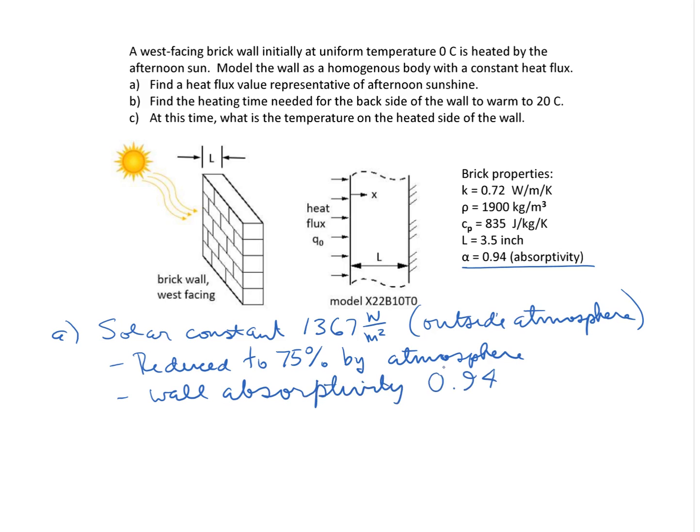And we've got some geometry here. If the sun were right overhead, that would be noon here. If the sun were down here, this would be 6 p.m. Let's say that the sun is somewhere in the afternoon, call that 3 p.m. And somewhere around that time is where we're going to assume that we've got the sun shining. So we need an angle adjustment, 45 degrees, to get the component perpendicular to the wall.